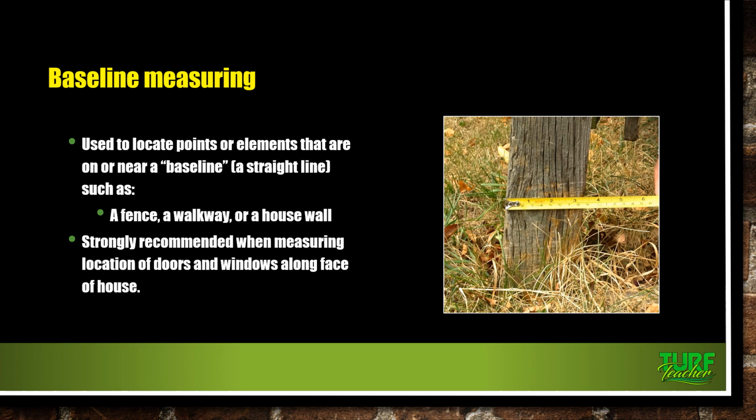Times have changed. Baseline measuring is used to locate points or elements that are on or near a baseline, a straight line such as a fence, walkway, or a house wall. It is strongly recommended when measuring the location of doors and windows along the face of the house.